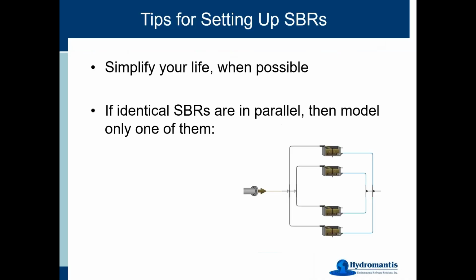I'm going to touch on, well, most of the important things, various tips for setting up your SBRs. So one thing that I often recommend is as a way to simplify things whenever possible, now we always recommend that in general, is to actually not model all of them in parallel if you don't have to.